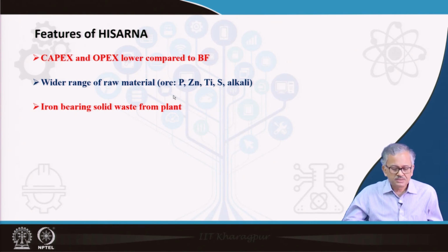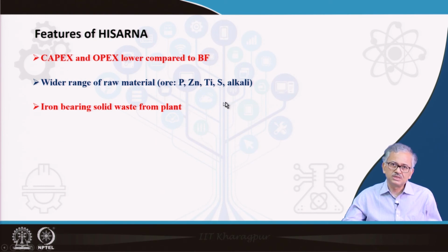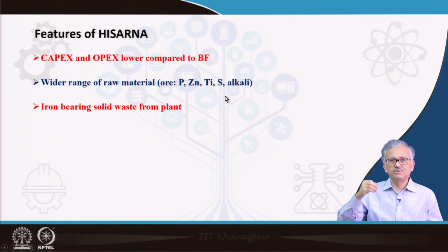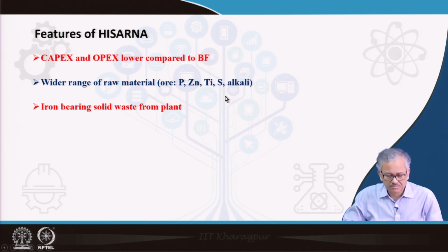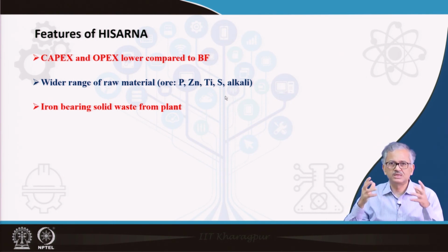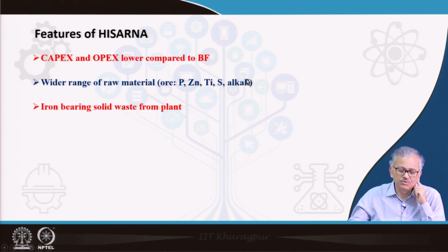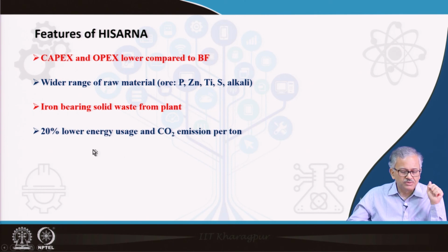But in this case, because these constituents are there in the iron ore bearing ore also, they can be vaporized and go away from the system. Absolutely no problem, because here there is no shaft furnace, so shaft furnace related problems are not there. So, any kind of ore you can use, and iron bearing solid waste from the plant you can use,